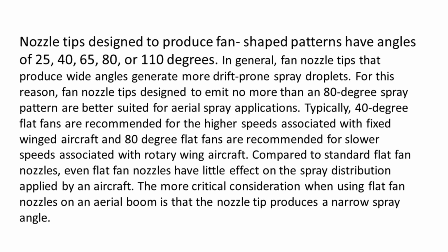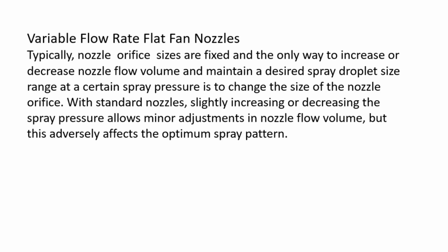spray applications. Typically, 40-degree flat fans are recommended for the higher speeds associated with fixed-wing aircraft, and 80-degree flat fans are recommended for slower speeds associated with rotary wing aircraft. Compared to standard flat fan nozzles, even flat fan nozzles have little effect on the spray distribution applied by an aircraft. The more critical consideration when using flat fan nozzles on an aerial boom is that the nozzle tip produces a narrow spray angle.